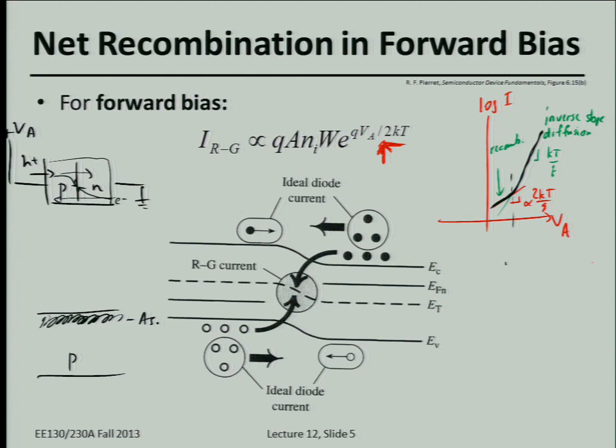So it is important, for eventually forming an n plus p junction, to minimize the number of crystalline defects right here, because that is what will lead to high junction reverse bias leakage current.